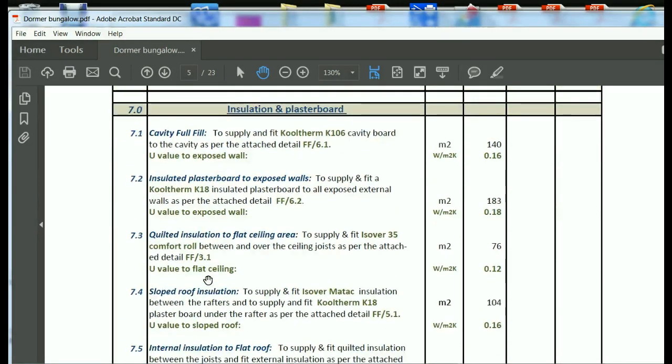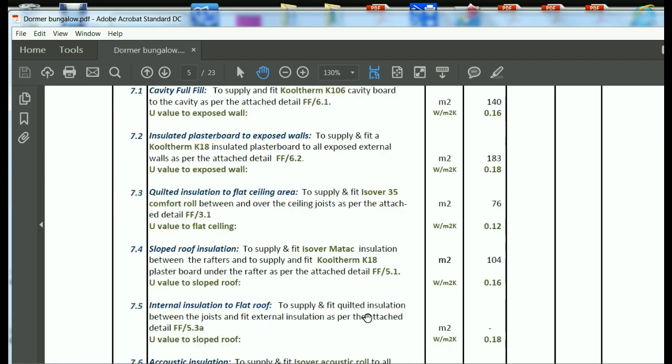The insulation. The bill describes each item of insulation. It gives the U value worked out by our technology that is needed to achieve compliance. It references the thermal bridge details. These details show how the insulation should be fitted, describing the structural and insulation material to use.